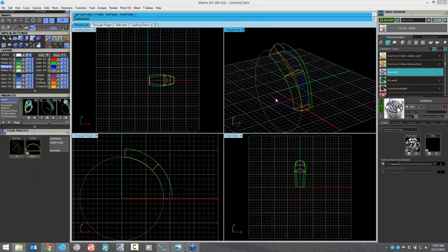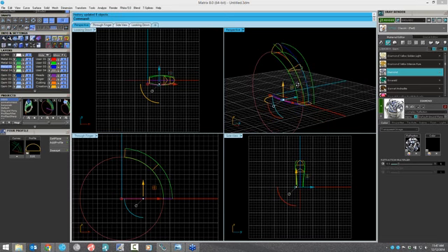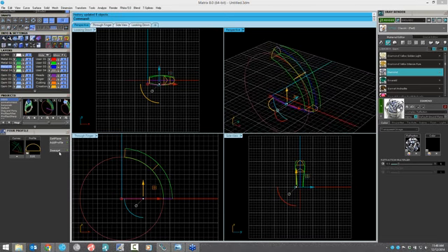the first thing I'll show you is if we come over here and move this, then you can see it sit and update those profiles through the rails. Let's go ahead and sweep this though. So now if we come over and say sweep 4, okay, select the profiles that are part of this sweep 4. So only the profiles. We already know the rails. Okay.